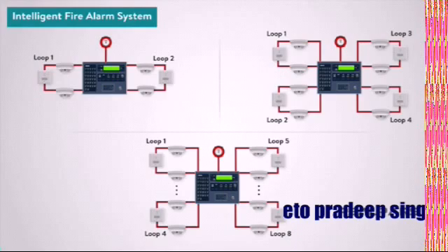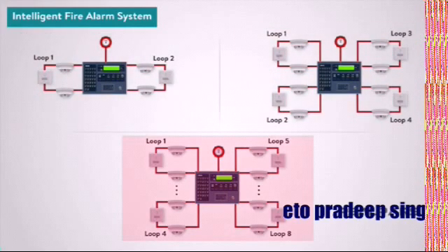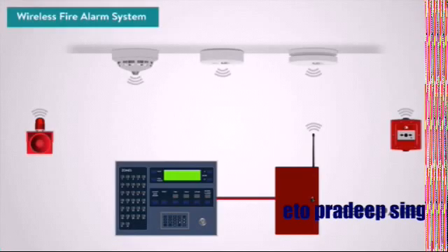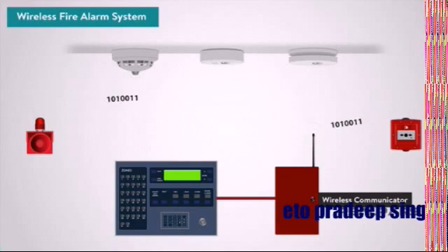Intelligent fire alarm systems are available in 2, 4, and 8-loop versions, which means large premises can be monitored from one single panel. The final type of system we will consider is the wireless fire alarm system. These are an effective alternative to traditional wired fire alarm systems for all applications. They utilize secure license-free radio communications to interconnect the sensors and devices with the controllers. It is a simple concept, which provides many unique benefits and is a full intelligent fire detection system without the need for cabling.